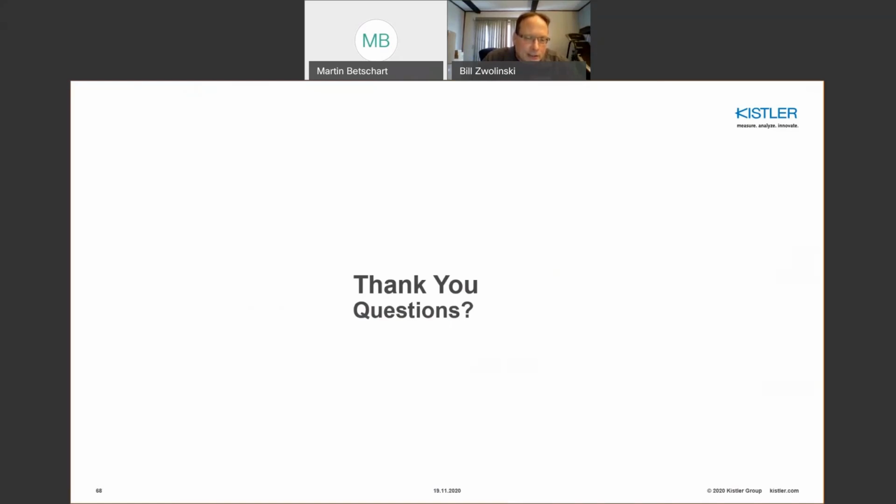Drift again is there when you have a long time constant, quasi-static operation. But drift is a function of sensor sensitivity. Some sensors have higher sensitivity than others. So the one I mentioned, the 4 picocoulomb per newton, gives you about a half a newton per minute, and that's your nominal sensitivity. You're rarely less than that, and usually more than that in other sensors. So that would give you an idea from a force perspective of what the drift might be.